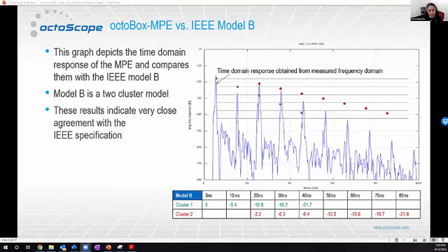There's another question, Steve, about the propagation delay for line of sight. And so that's pretty much in nanoseconds because it's a passive system. There's nothing active. There's no demodulator, remodulator. There's no sampling. It's just RF.